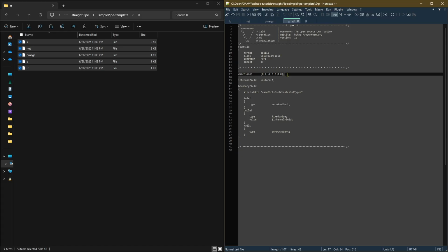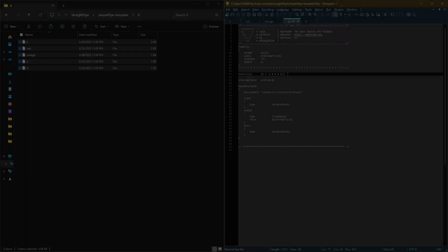Kinematic pressure being static pressure divided by density. This is again useful because when we visualize our results, we will need to multiply that with the density of our fluid. We initialize it at 0, and essentially the inlet is kept at zero gradient, same as the walls, and the outlet is kept at a fixed value. The value 0 here essentially indicates atmospheric pressure for our instance, since the static pressure is for our instance equivalent to gauge pressure. This is because we are operating in atmosphere.